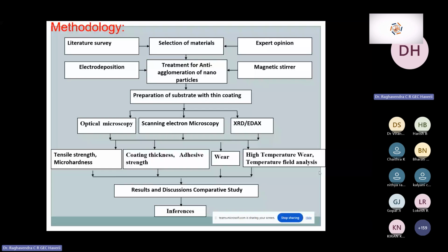It refers to the strength with which the coating has bonded with the substrate material; that is what we call the adhesive strength. There are different techniques used to check the adhesive strength of the coating. One example is the scratch test technique, wherein a diamond stylus indenter is made to move on the coating surface, and a ramp load and a constant load are applied. The ability to resist the scratch gives us the adhesive strength.